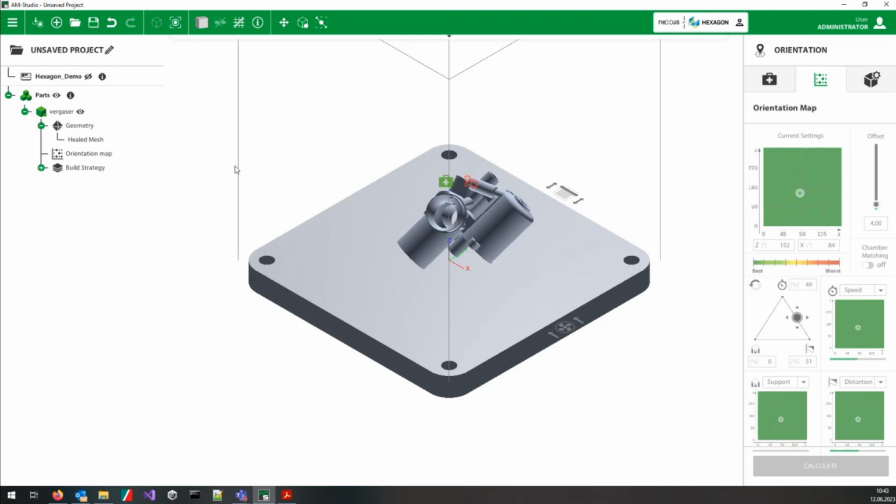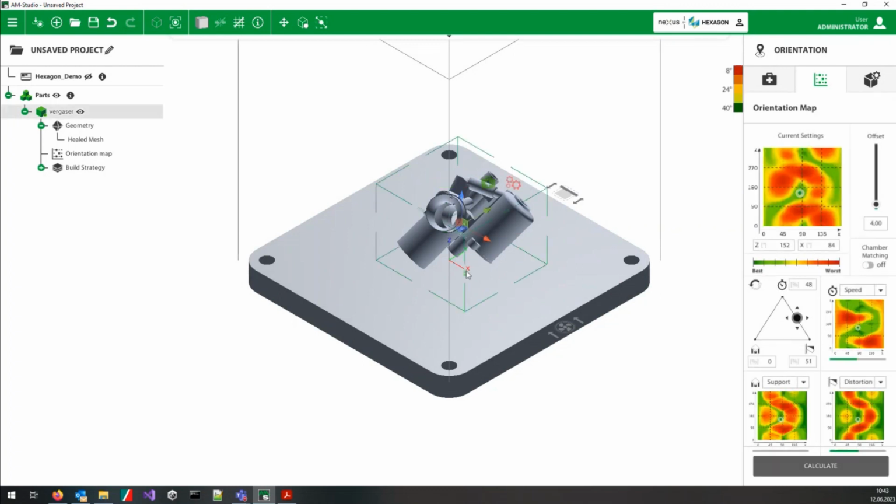Clear. So the last question for now: calibration strategy. In SimuFact Additive, we use a different calibration approach. Just 2 coupons in the middle, and we get the inherent strain values, and we use those for analysis. Yeah, I've seen a similar calibration approach. So I think we can configure that cantilever position, right?